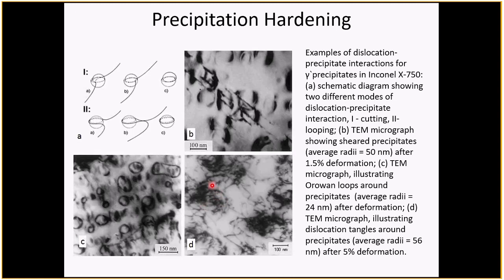And this is what the structure looks like probably because the stress is not high enough, so you have some slip formation, and you just get the dislocations tangling up, and the material starts to harden. But you haven't got to that point where the stress is high enough to cause either this or this. And of course, once you get this tangle formation, that in itself will harden the material just from the forest interaction.